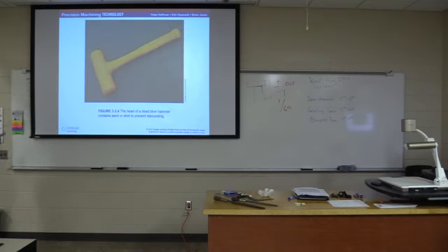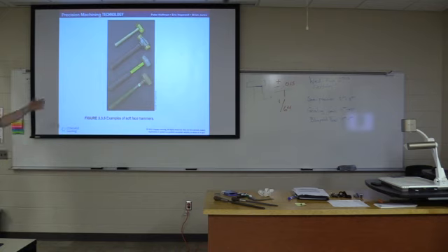These are dead blow hammers. We have some of these laying around. These are the preferred hammers for adjusting vices. They are plastic, so they won't ruin the steel. Different other kinds of soft face hammers.